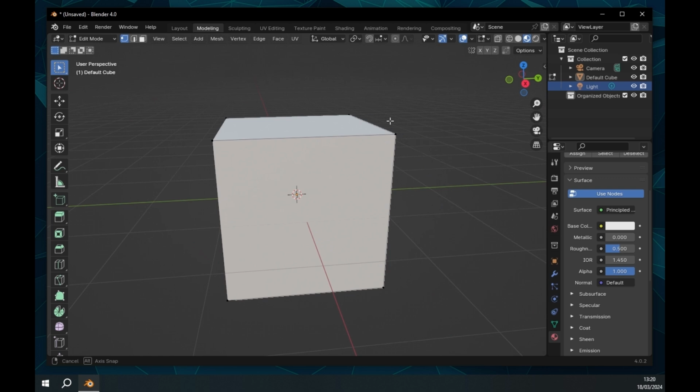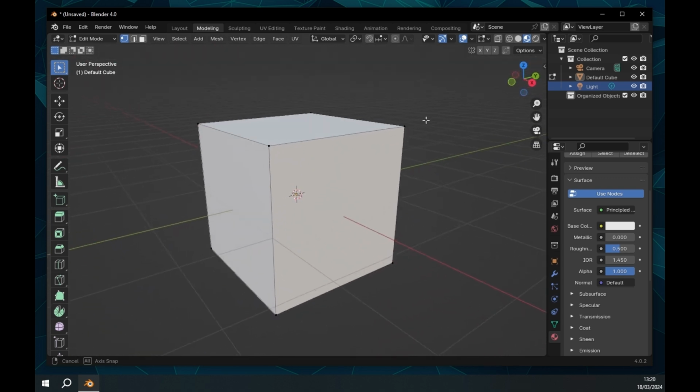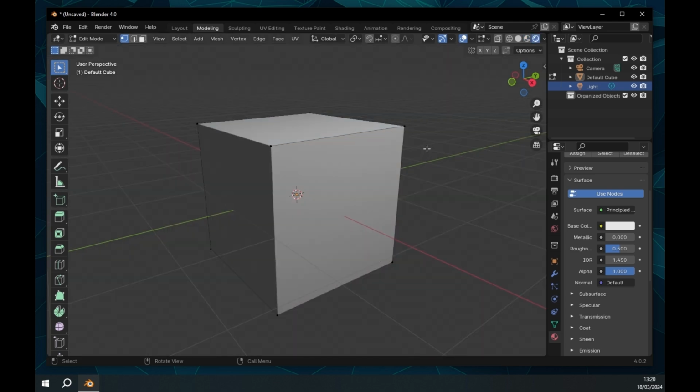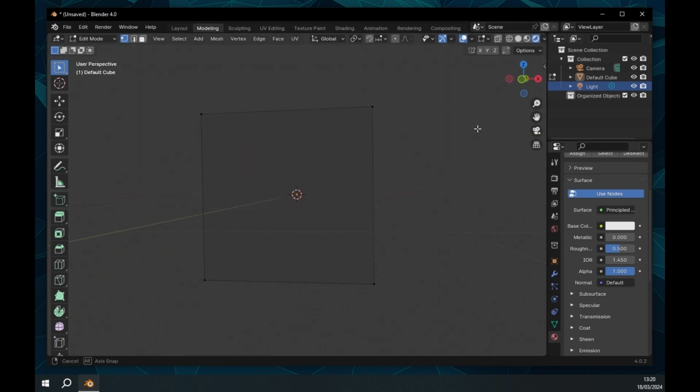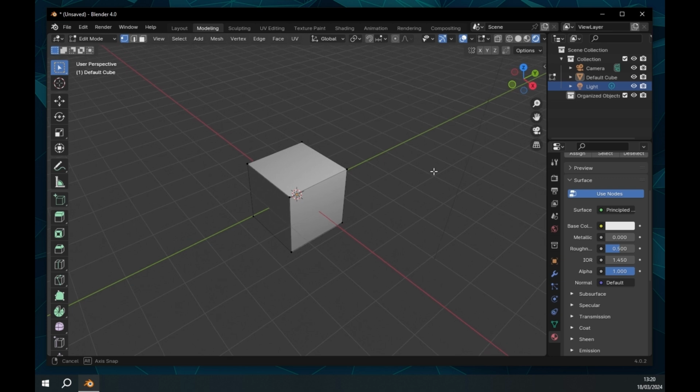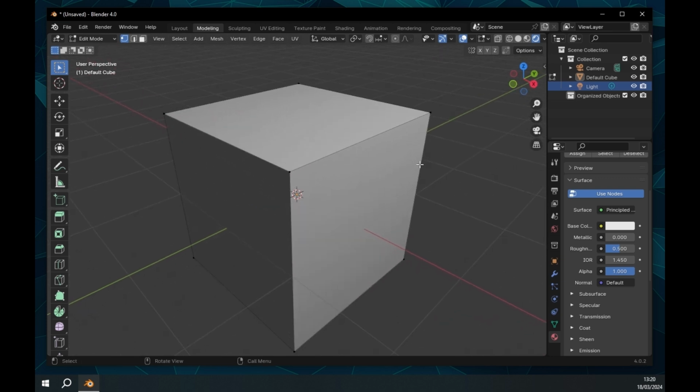Material Preview mode allows you to see your object with its materials and textures applied only. Render Preview mode applies everything, from materials to shadows, light objects and even reflections. You can use this mode to take a look at your scene before exporting a final render. In this case, we can see that the default light object is affecting our cube, giving it a shade.